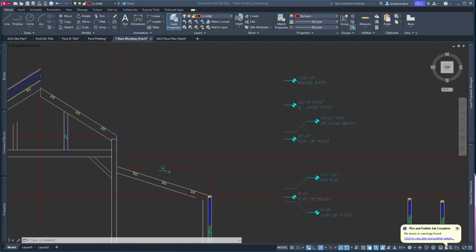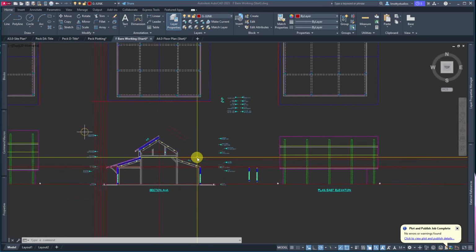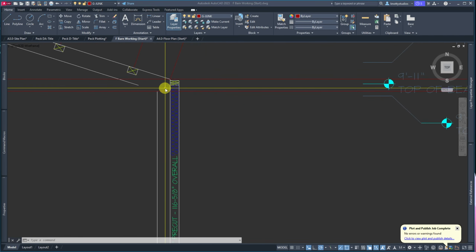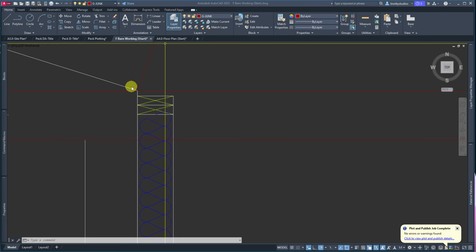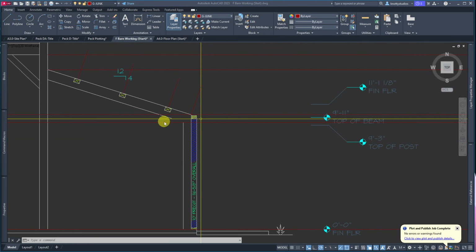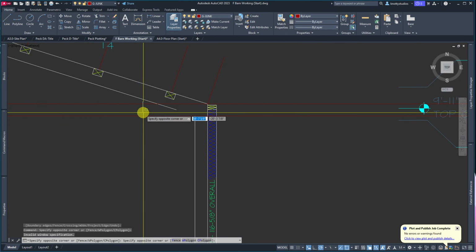So that needs to be definitely investigated. So now that I have this down here and it's getting pretty set as to where it's going to be, I'm going to say that a 10-foot precut's not going to work in here because it's not going to be able to plane out. This means we'll have to cut a little bit off, drop the wood a little bit. So it's not a detrimental factor.